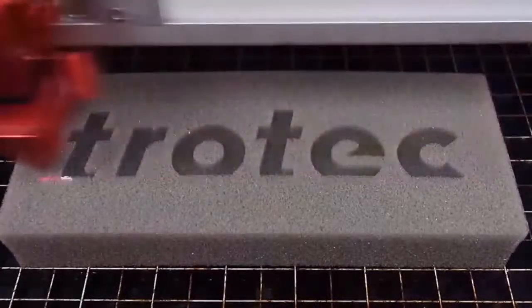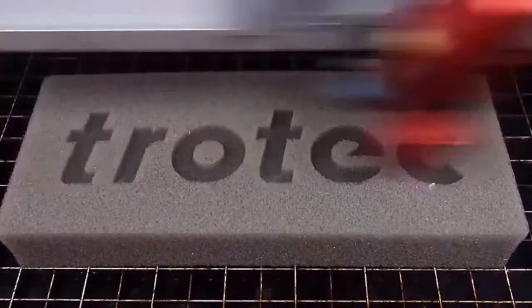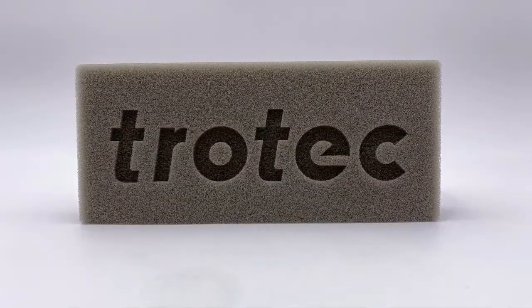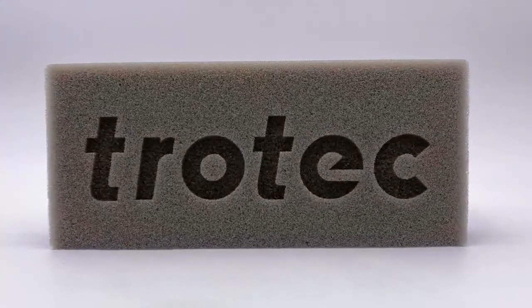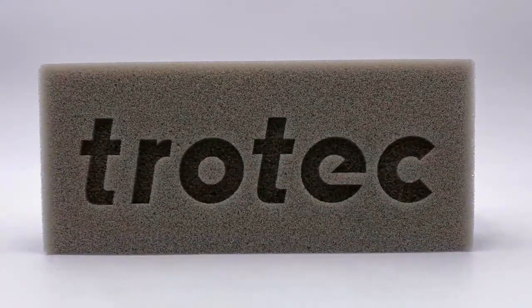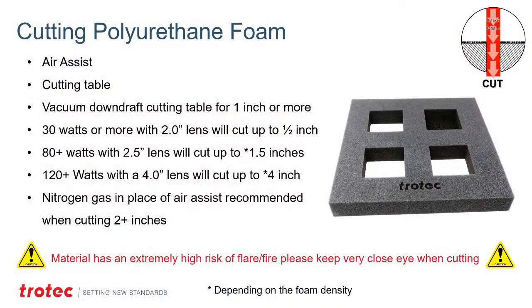So we're engraving it. There's no time lapse on this. The laser is able to vaporize it because we're taking such a short amount of passes. Now we get that nice depth contrast into the surface of the foam. It's a great material to work with if you want that contrast into it. But it does have some limitations, and that is mainly in the cutting side. So engraving it works good.